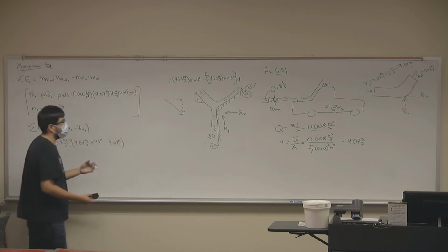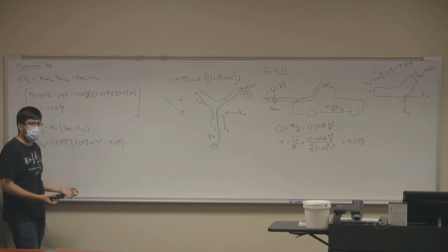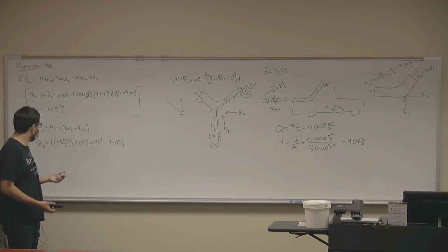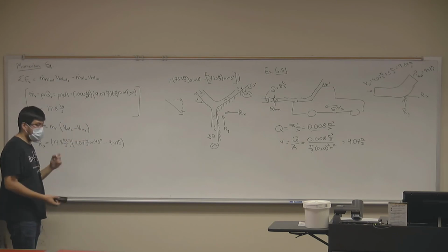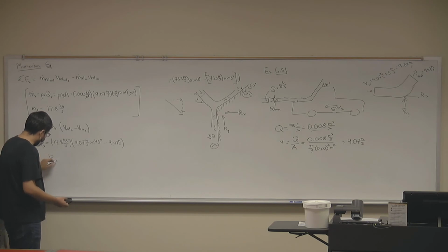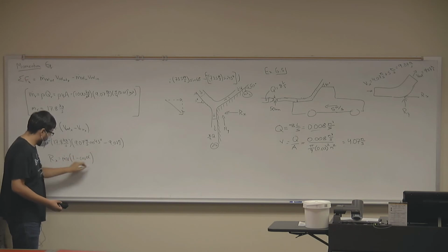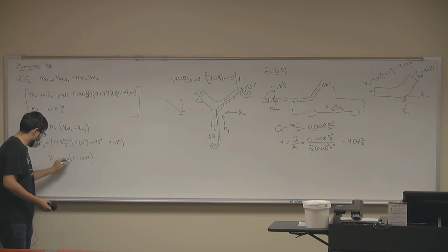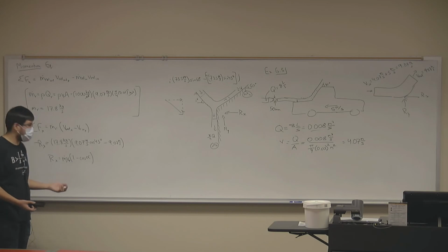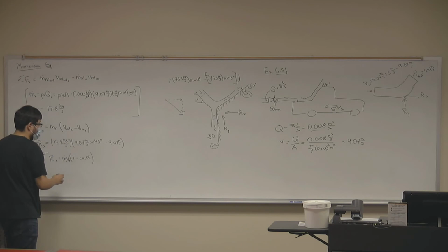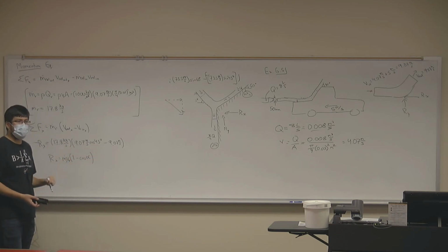At this point, because this is a very standard deflector, you can just apply the equations of deflection that we derived earlier, right? The equation that we got earlier was Rx equals mass flux times velocity times 1 minus cosine of alpha. Notice that if you understand that the mass flux and the velocity are relative terms, the equation is exactly the same. Mass flux times velocity, you get cosine of alpha minus 1, but there's a negative sign, so you flip these terms to turn it into a positive. So it's the same equation, except that we're dealing with relative terms. You choose whatever method is best for you.